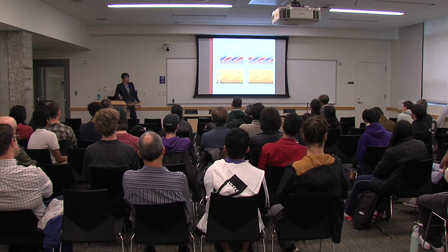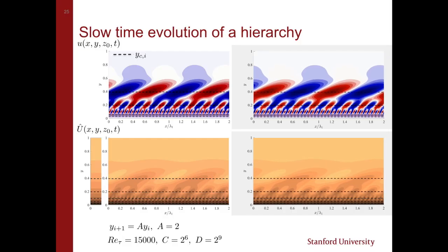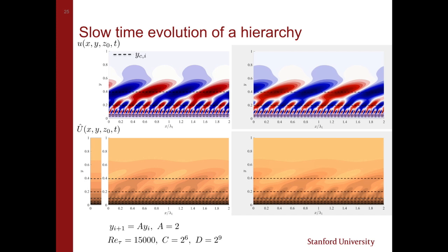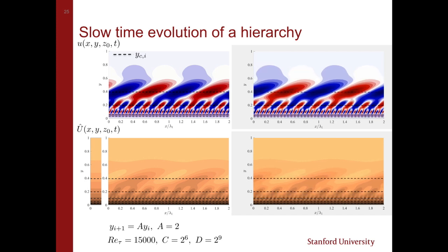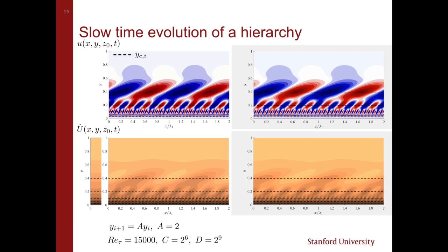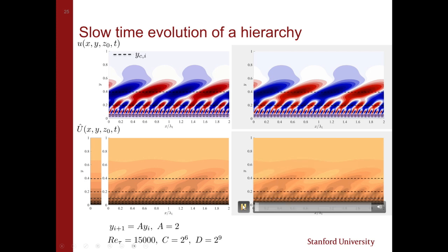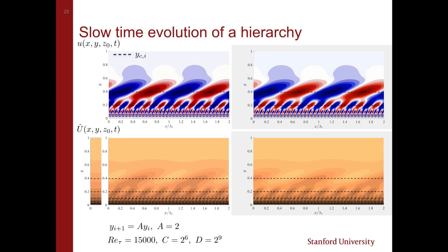And again, if I add in the turbulent mean, first thing you see is that bulging that we saw happens across scales, right? So now we have something that would look a lot like those uniform momentum zones. Too clean, because I only have one hierarchy in here as opposed to thousands of different modes. But I have something still evolving that has at least the same type of behavior. I want to play this one again, because if you look really closely, there's something interesting. Because the top one is moving faster than the other, the structure is always self-similar, but it actually evolves a little bit, right? Because this one is moving faster than this one, etc. So at any instant it's self-similar, but it's a little bit different.